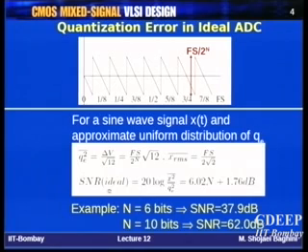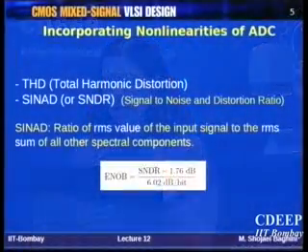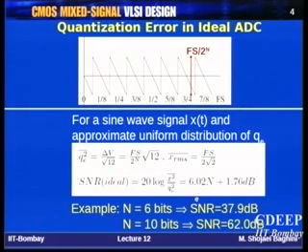If the signal is not full scale, you will have less SNR, and it increases with the signal amplitude. Ideally, you get maximum SNR when the signal amplitude is maximum. Now, if your SNR reduces, why? Because now instead of SNR, you have SNDR. It means that your signal power to noise and distortion ratio is less than what you expected, even for a full-scale input. This means you don't expect to get the same resolution you had before. That's why we define the effective number of bits. It's the same relation, you just solve it for n as a function of SNR.